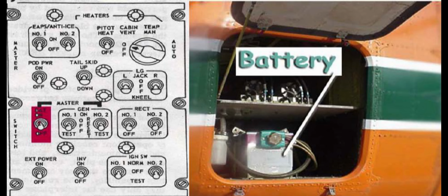DC system theory of operation. The DC system power is supplied by two 28 volt, 200 ampere converters, which are transformer rectifiers. Power is distributed through a primary bus. Operation is automatic. The primary bus supplies all equipment necessary for maintaining normal flight.